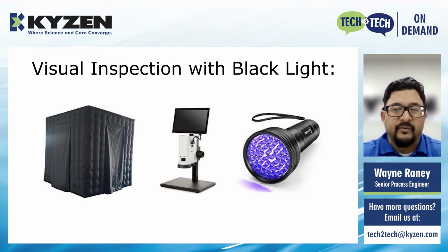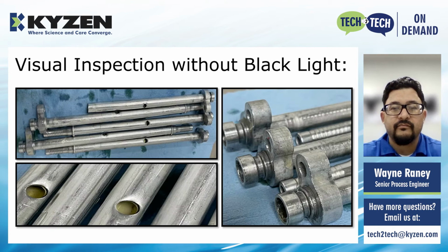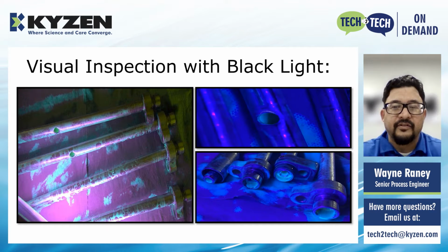So to be able to perform the visual inspection with a black light, we need to have two of the three elements shown here. So we'll take a sample of the parts that were washed in a dark space. Once inside, we'll turn on a black light and proceed to inspect the parts. And with the help of the microscope, we can make a more precise inspection. In this image, you can see some parts covered with oil which have not been washed. I just want you to pay attention to the inside geometries. Here we can observe the same parts using a black light, and we can see how the black light highlights the oil residues on the parts.